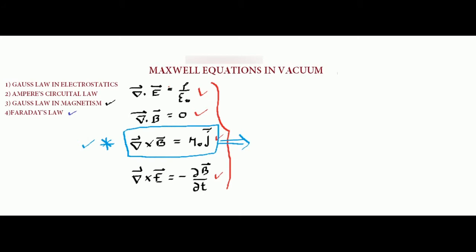He said, let me look at Ampere's circuital law. It says that if you have a wire carrying a particular current I, then this current-carrying wire produces a magnetic field which is circular by nature. Great. And Biot-Savart's law gave us the formula, which says that the magnetic field is mu naught I divided by 2 pi r, where r is the radius at which you are finding the magnetic field. For example, from here to here this can be r, or if you are calculating around a bigger circle, then this can be r. So r is the position at which you are calculating your magnetic field.